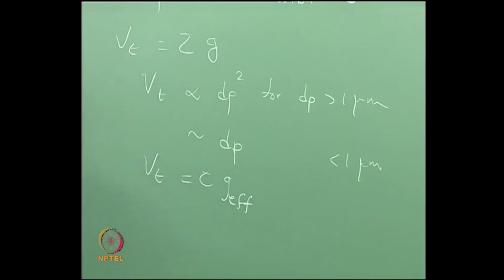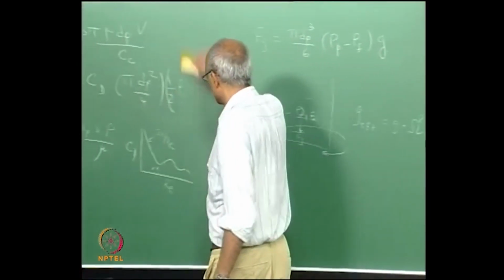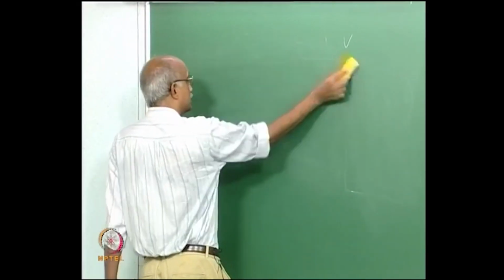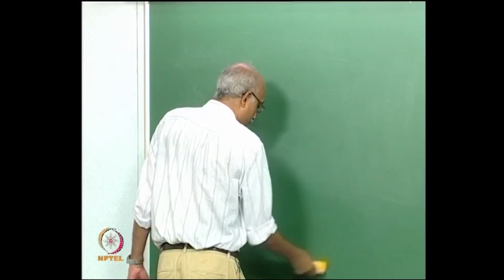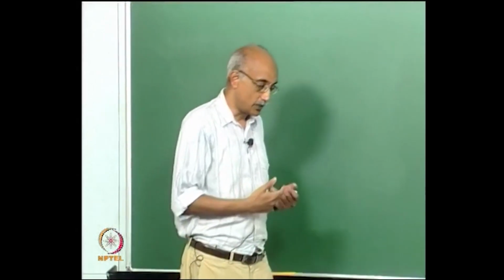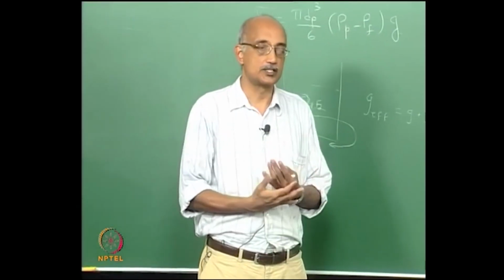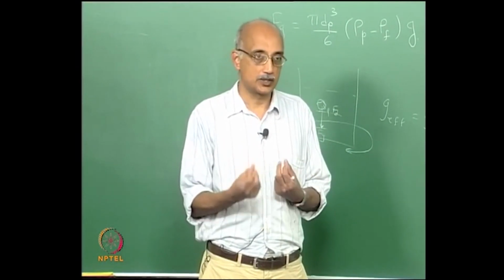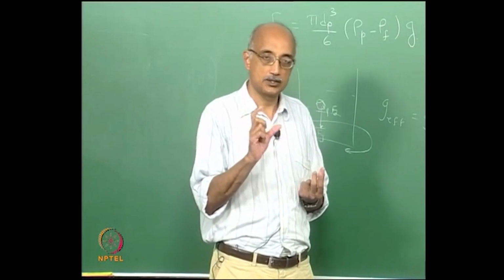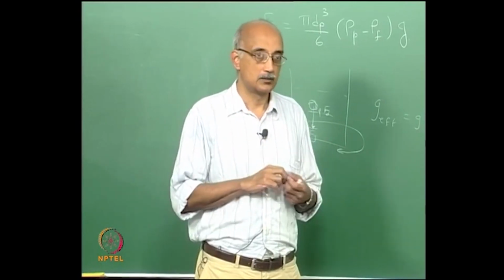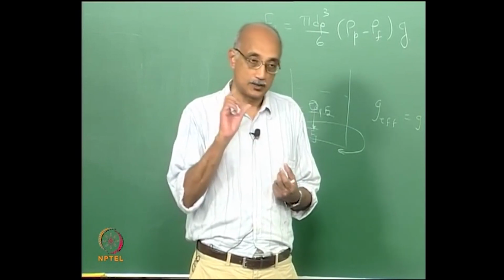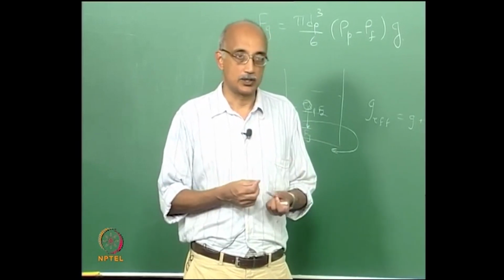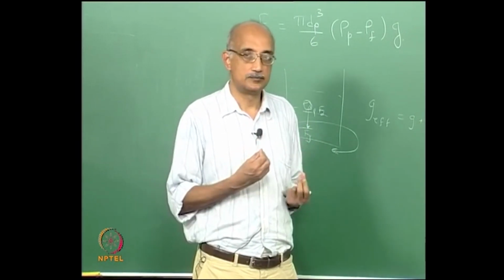Okay, now let us look at how this leads us into our definition of a dimensionless parameter that governs inertial transport of particles. As I mentioned in the last lecture, as particle size changes, so does the predominant force field. So, when particles are very, very fine, diffusion and electrostatic effects dominate. As particle size increases to an intermediate region, drag begins to make its presence felt. As particle size increases beyond that to supermicron values, then inertial effects begin to dominate. So, what do we mean by inertia?